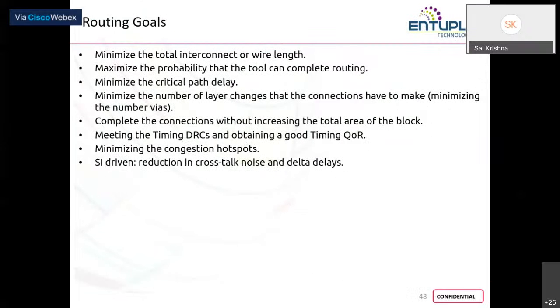Yes. So along with all of this, another couple of important points that you have to note is that whatever routing you do, it has to follow your DRC rules. DRC is design rule check. That means there are certain dimensions given in your LEF file, actually given by a foundry anyway. But the thing is, the minimum dimensions that your foundry specified must never be violated.